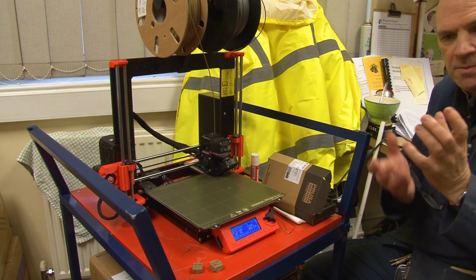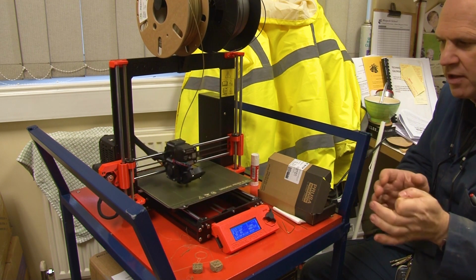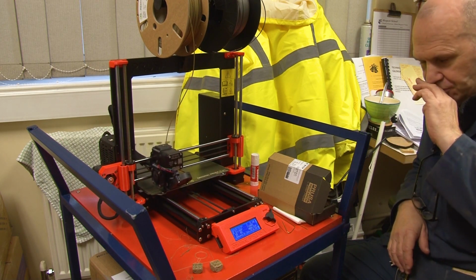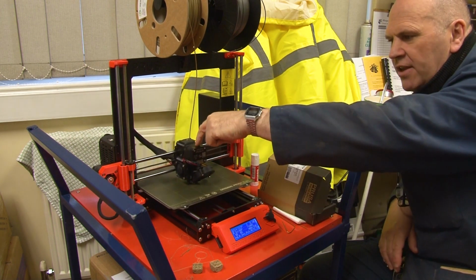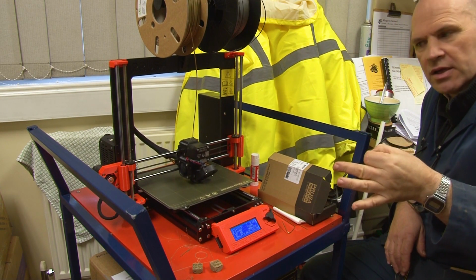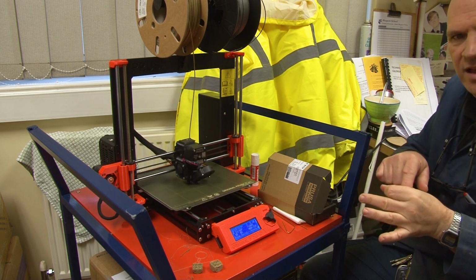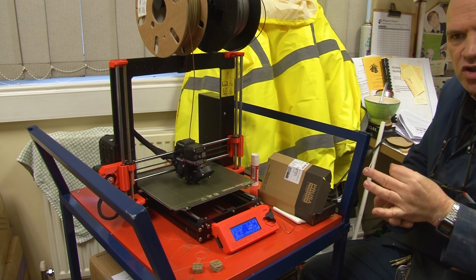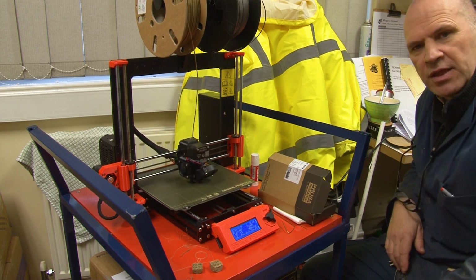The nozzle is a bit like a funnel, wide at the top, coming down to a tiny little point that's probably less than 1 millimetre in diameter. If you leave the machine on, that hot head under there is staying hot a lot. And eventually it cooks the plastic, and the plastic starts to bake to the inside of the nozzle and makes that smaller and smaller until eventually it's just not going to print properly.